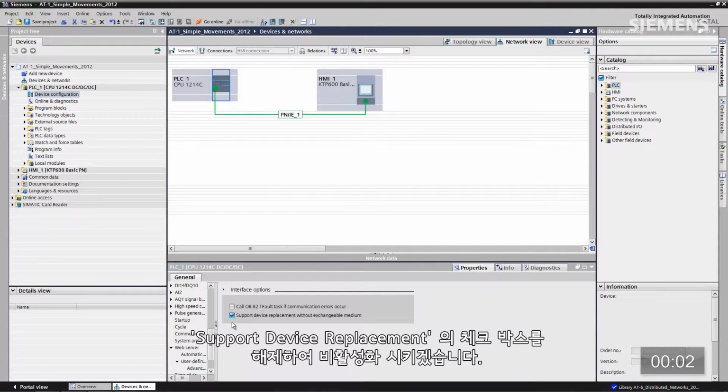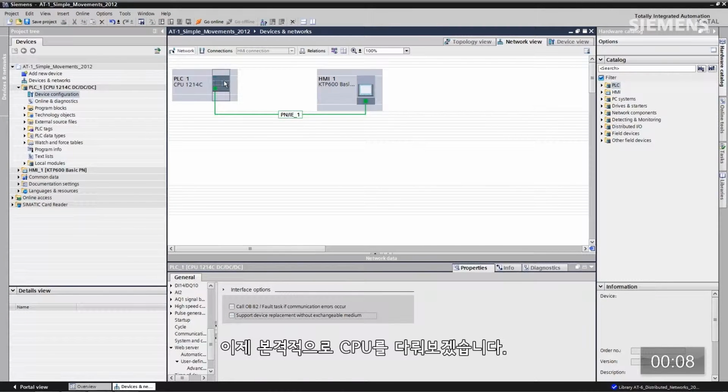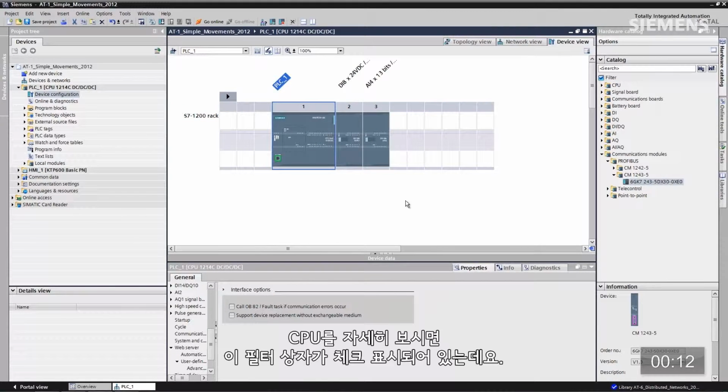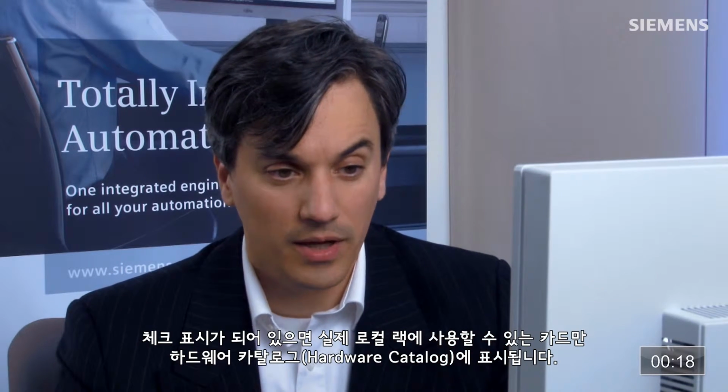I want to give focus to the main CPU first, and I want to check off this box of support device replacement because some field devices don't have that capability. Now I want to give complete focus to the CPU, so I double click on it. The moment I've got complete focus on it and this filter box checked, that means that only the available cards for this actual local rack are available to me in the hardware catalog.